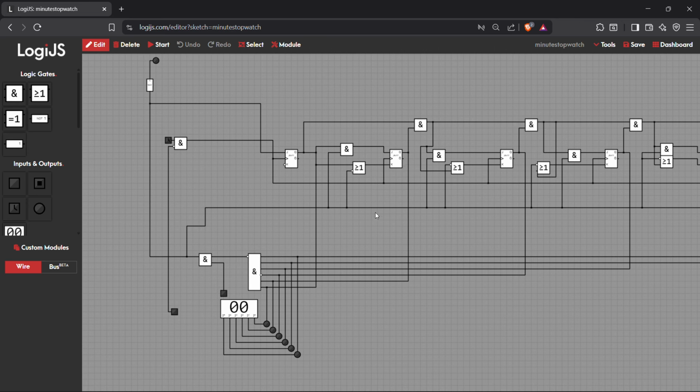So that's why we are using the reset signal. And now the output of flip-flop 1 will be ANDed with the previous flip-flop so that the next bit could be triggered. If these two outputs are triggered, then only will the third bit trigger. Then only the third bit counter will start moving.